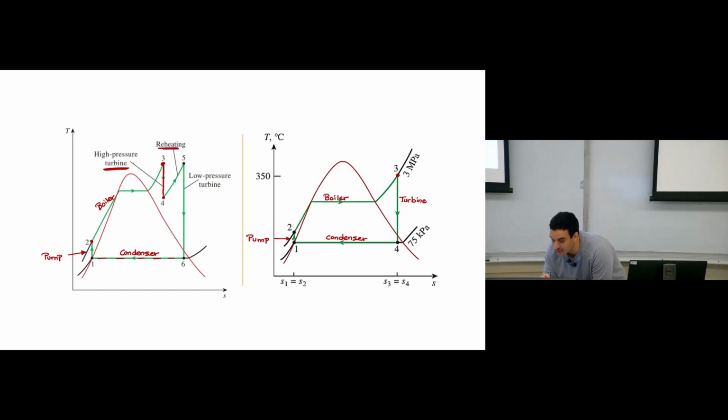So we have a reheating happening. We have a temperature increase one more time up to a certain point, and then once we reach this point, we have isentropic expansion happening, so this means we have another turbine. See the change we have here in the TS diagram. We don't have a single step expansion. The outlet of the boiler is not subjected to a single expansion directly to the condenser pressure. It's expanded to a certain pressure value, then we reheat it again, then we expand it again.